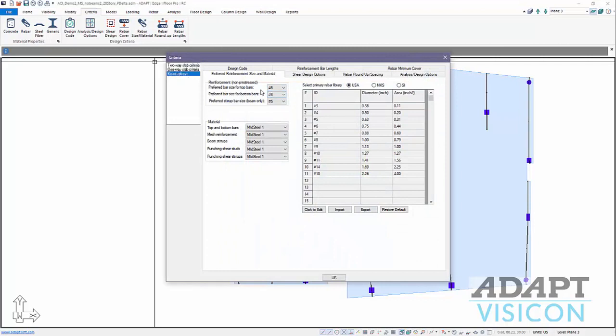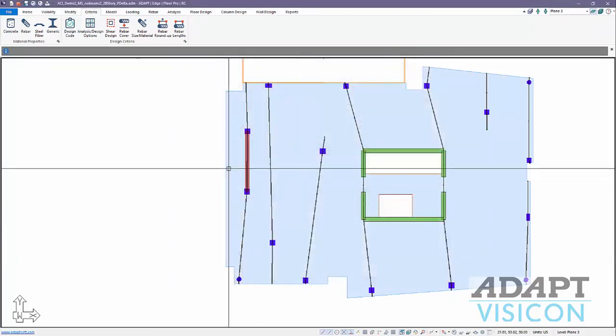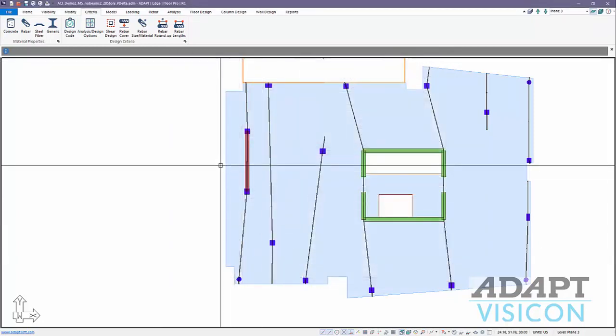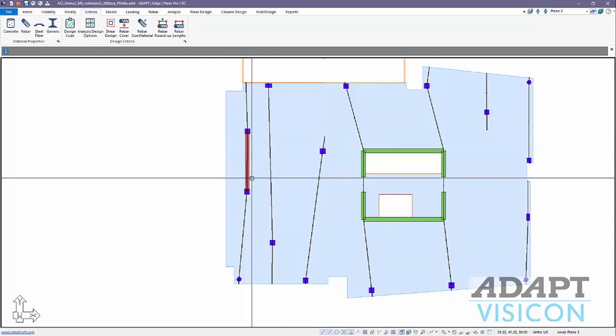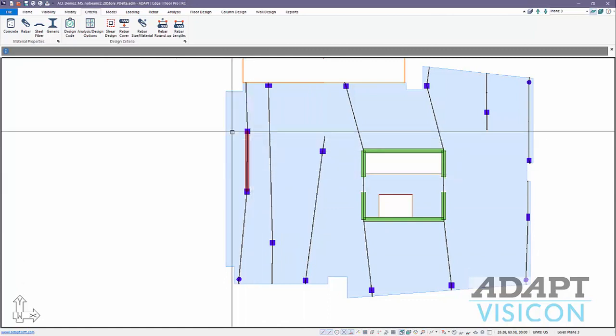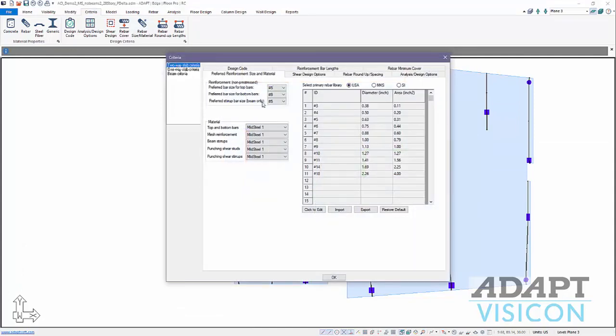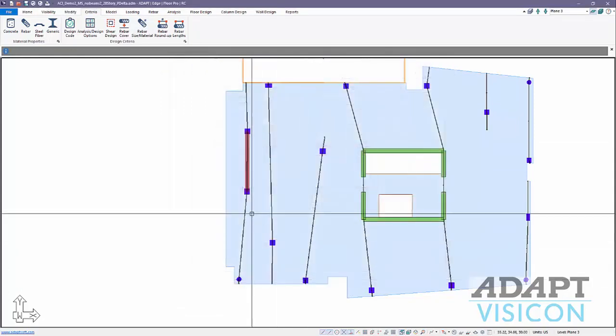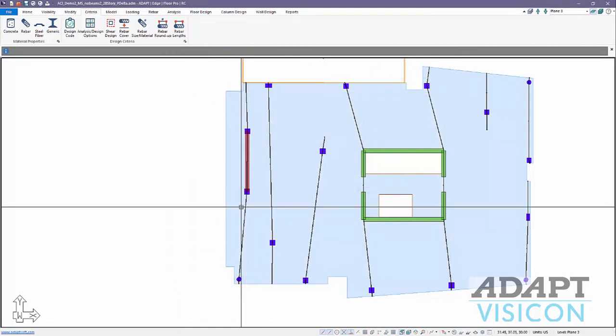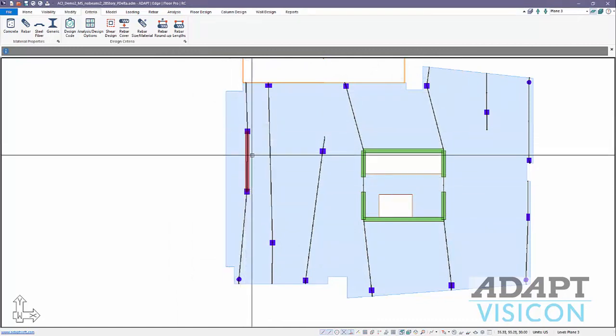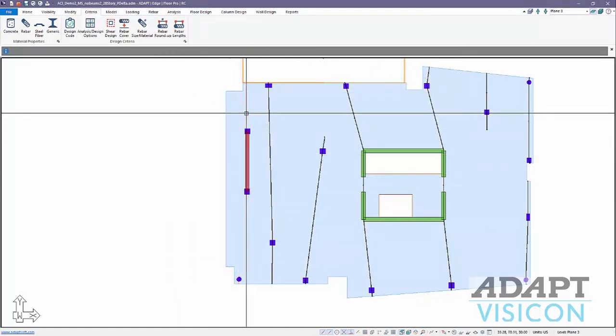For beams, we actually might want to use number 9s, for example. So the program, again, designs the proper amount of area of steel, but the rebar assignment to the beam takes on the characteristic setting of a two-way slab size. So these sizes here. If we want more explicit control of that being labeled as a beam, we can do that using the new editor.